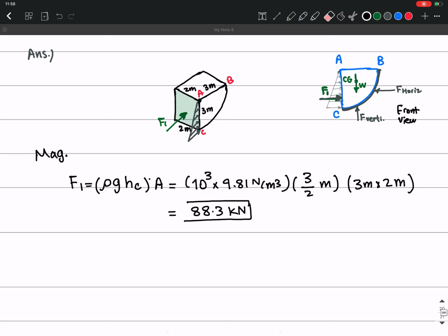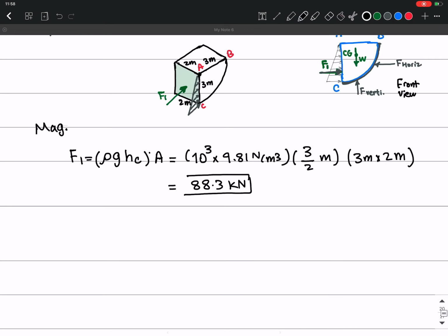But another way to solve it is as follows, and this is how I also calculate sometimes myself. I say, okay, I have this much force, and at the bottom, the highest one is rho g times 3 meters, and here I have 0.